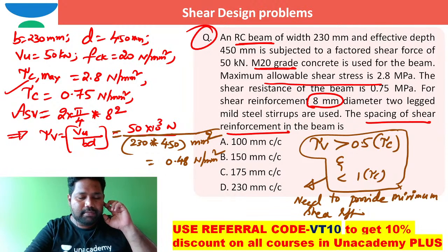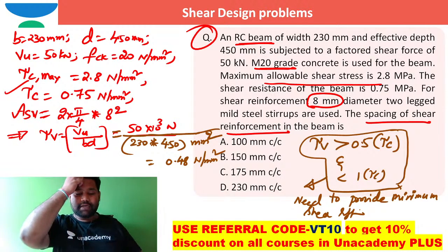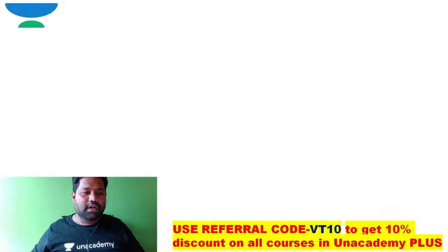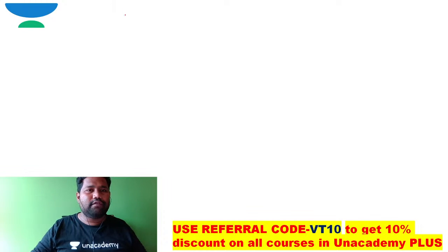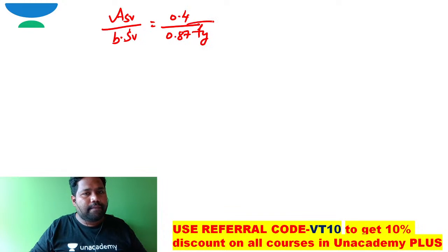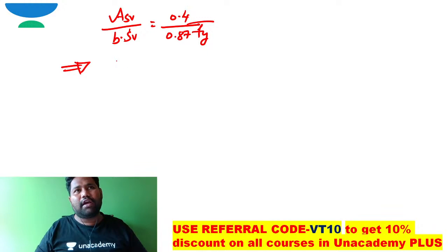How can I design that minimum shear reinforcement? In the next slide. So what is the equation that we can use for minimum shear reinforcement? It is Asv by B into Sv equal to 0.4 by 0.87 fy. So coming to Asv, it is the cross-section area of the shear reinforcement, which is a two-legged stirrup now.